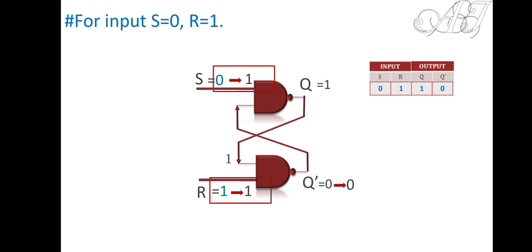Okay, and by the time the input of the first NAND gate is changing, because of that propagation delay, this 0 that we have got here will travel through this path, and this will reach here. So that will make the input of this NAND gate equal to 1. Why? Because one input of this NAND gate has become 0. See, this 0 will travel through this path and will arrive here.